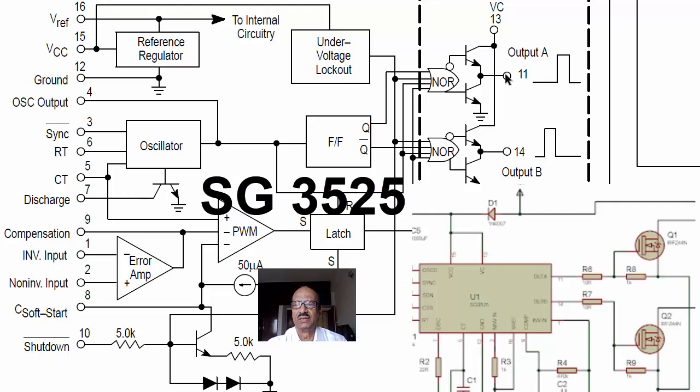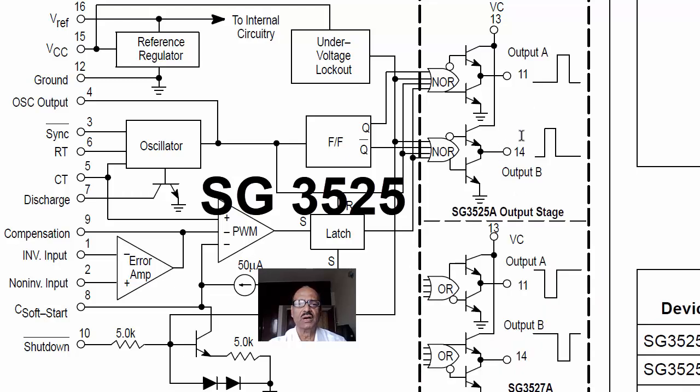the MOSFET. And the biggest advantage of the MOSFET drive here is that when it goes positive, and then when it goes negative, it bypasses the capacitor and takes out the charge from the MOSFET capacitor very effectively, so that this can be used for high frequency operations and better reliability. Apart from that, the same thing of course for the other output. Apart from that, the other things are almost the same.